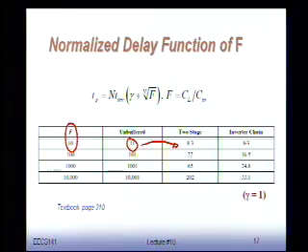So in this case, 2 inverters is the optimal solution. But now you can see if I start increasing capital F, let's say, a factor of 10,000, we see that the unbuffered delay will be 10,001. That would be huge. It will be an enormous delay. If I have a very tiny inverter driving that huge capacitor, it's going to take forever. If I take 2 stages, just adding 1 extra inverter already goes down from 10,000 to 202. That's a reduction by a factor of 50 in delay by just adding 1 inverter in between there.